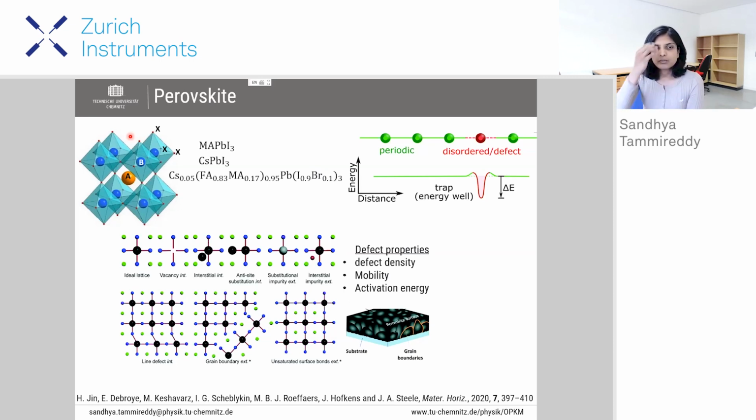So based on what material composition you use to fabricate a perovskite, they are called differently. For example, I have shown here the three ideal perovskite materials which are prone to lead to very high efficiencies. The first one is MAPI. In a brief expansion, it would be methyl ammonium lead triiodide perovskite. As you can see, it contains both organic and inorganic compositions together, so it's a hybrid one.